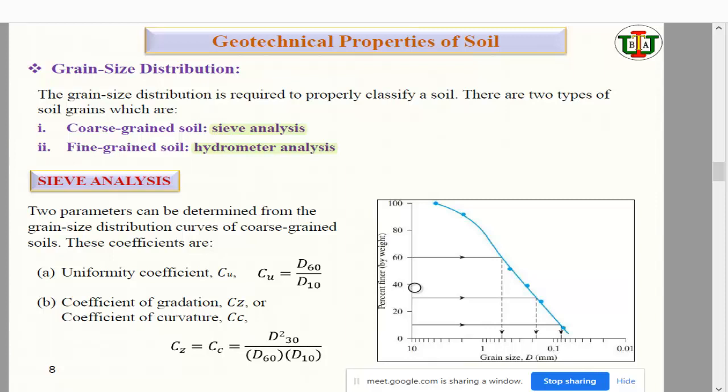There you found that if the material is well graded, there is a chance to have less void, right? There will be a higher rate of compaction while you do the casting. This is a very basic concept. So if the gradation curve is well graded, we have a higher chance to have less void, so our concrete will have more strength than void concrete.